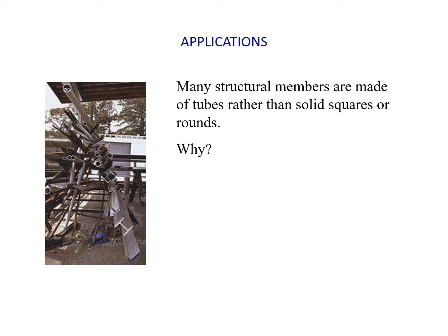It turns out that the answer to this is that the tube will have a lot of its area pushed out, a lot of the mass in the area out at the outer edges or the outer limits of the column. And it turns out that thrusting of the material away from the centroid is key to having the property that we're looking for to reduce bending.